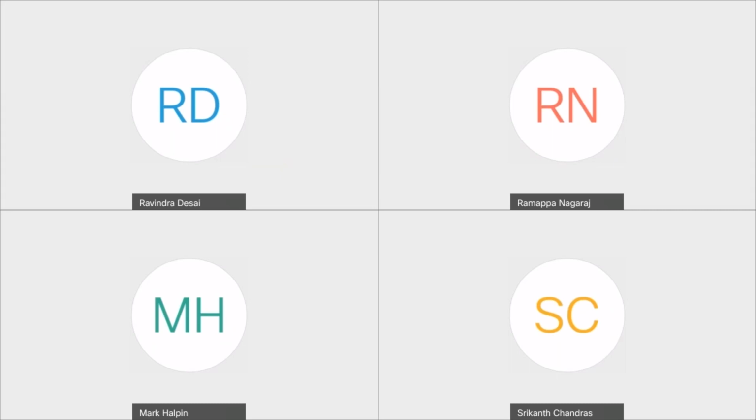And you have the traditional things like cycloconverters, and any kind of AC to AC direct frequency converter produces interharmonics. As far as higher order harmonics are concerned, any kind of modern power electronic converter is switching well into the kilohertz range.